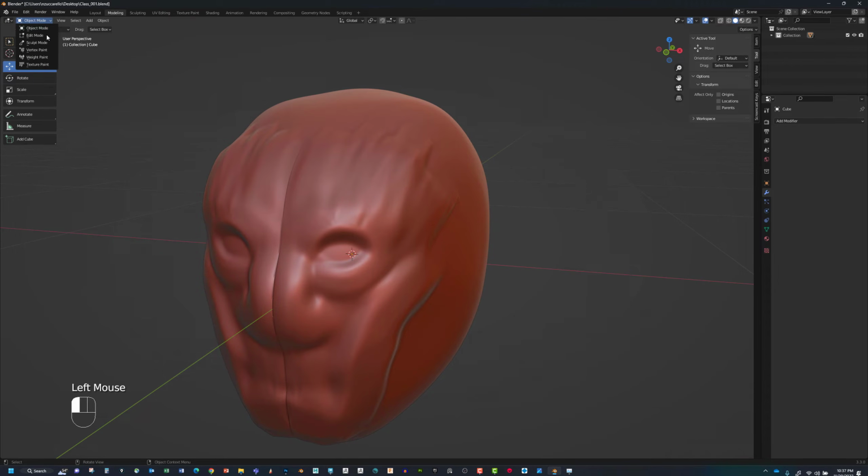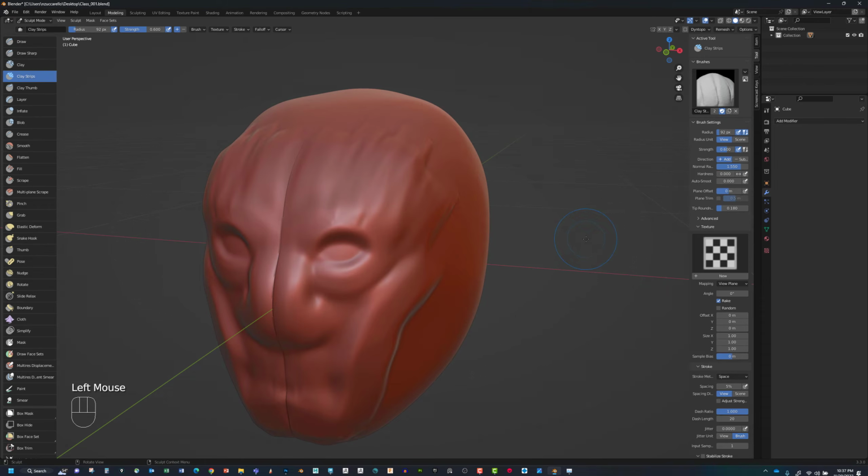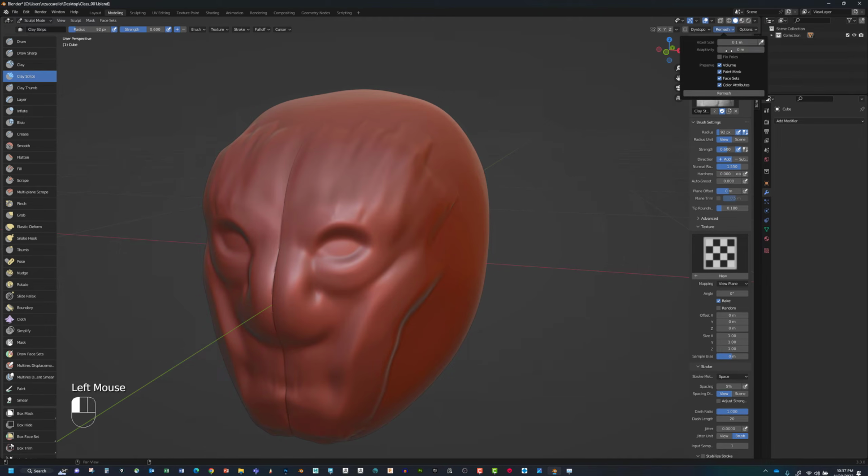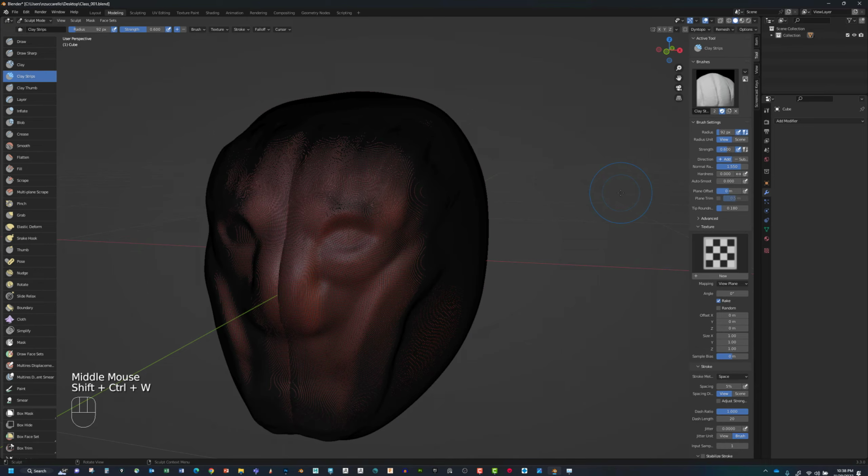So we can go to, instead of object mode, we can go to sculpt mode, put that in there, and then you can see they do have dynamic topology, and then they've got this remesh. And if we go ahead and click remesh, before I do that, I'm going to turn on my wireframe. So again, you might have put that on a quick favorite to toggle that on and off.